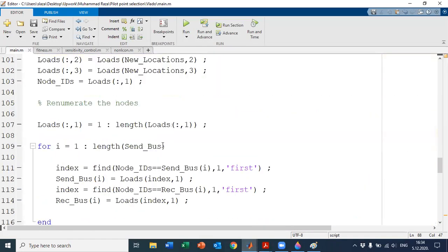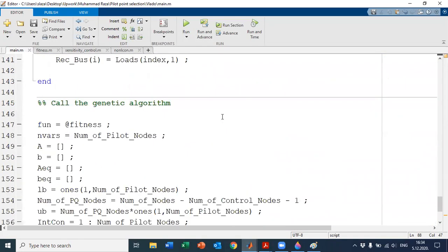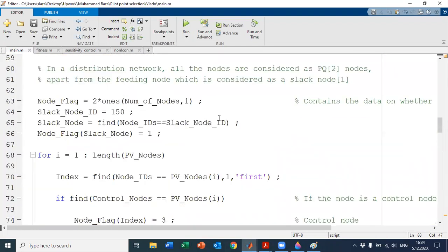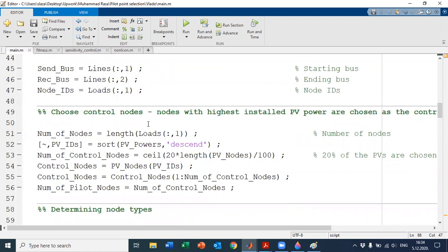And what do I mean by that? Simply, the PVs which have the highest power have the highest inverter power, which means that on cloudy days and on the days when there is not enough generation from the PVs, these inverters and these generators can give us the most reactive power. That is easy to understand. So basically, every solar panel has an inverter, and the bigger the solar panel, the bigger the inverter, meaning the bigger reactive power reserve.